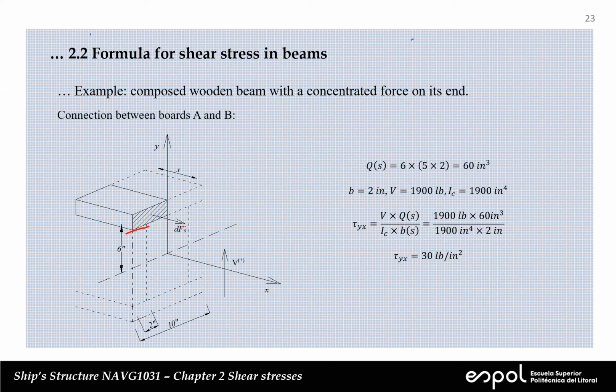And I'm showing you, since we are in the upper side of the section, the Y average is positive. The V, the shear force, is also positive. So this imbalance, axial imbalance force, is also positive, right? So on the lower part of this cut, we're going to have a shear stress which points in that direction. And that's what we can calculate.